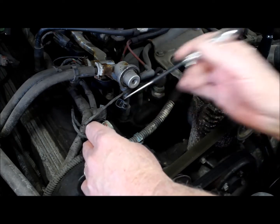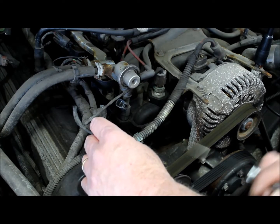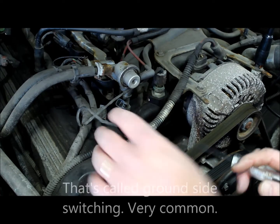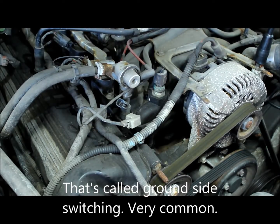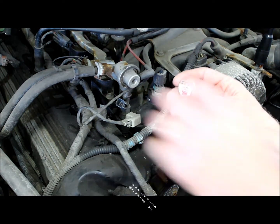So this red wire goes to all 8 fuel injectors, powers them up when the key's on. It's up to the PCM to ground the other wire in order to open the injector. How do we know if the PCM's doing that? We can use a Noid light.